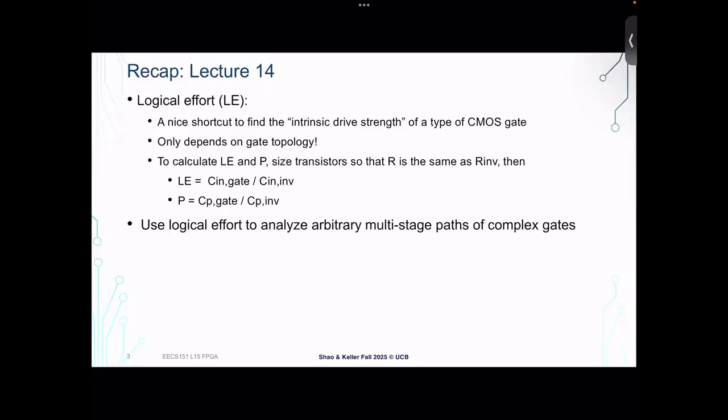But when you run in ASIC lab, when you run synthesis and it gives you a timing report and reports the delay of a path, it's doing a version of that analysis effectively, right? Where it's figuring out, okay, for this gate sizing, what is the delay? And therefore, in the synthesis optimization loop, how should I size the gates? There's a lot more details going on under the hood, but at a high level, it's similar to what we did in lecture.